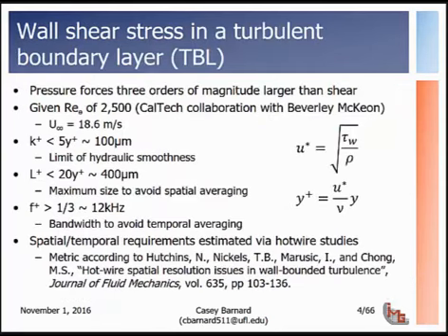Part of the reason for that is some of the requirements of this kind of measurement include being highly resistant to pressure. In turbulent boundary layer areas, your pressure forces are often 3 orders of magnitude higher than shear. But because it has to be a directly exposed sensor, if you're doing a direct solution, you have to be highly resistant to that kind of cross-axis input.